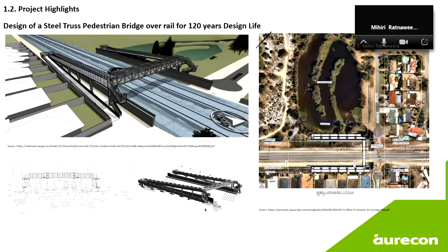Because what happens is you're trying to introduce a splice connection in the middle of the bridge that will encroach into your minimum vertical and horizontal clearance underneath, as well as inside your steel truss. So there's a lot of geometric play around, and every time you change your geometry, you change your entire design model and you add more self-weight to the truss. And that then turns into an iteration of calculation that you really don't want to do when you don't have time.